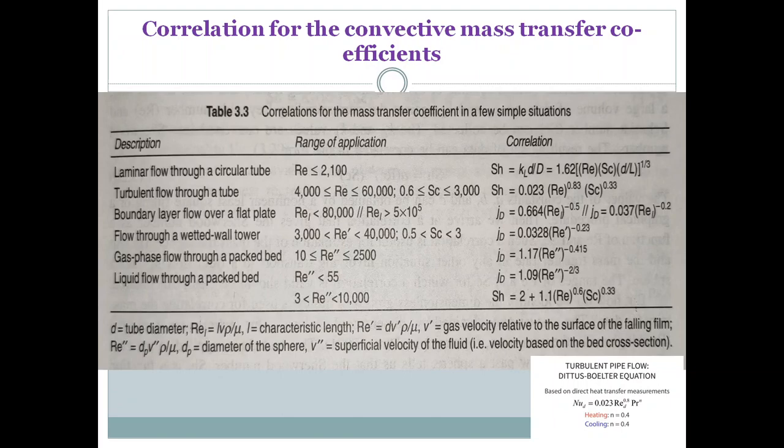I have to calculate the mass transfer coefficient, and we should calculate the delta, but we cannot do that directly. You know the mass transfer coefficient is expressed by delta, but the other things are not available. So how will you calculate the mass transfer coefficient? With these empirical correlations using dimensionless numbers.